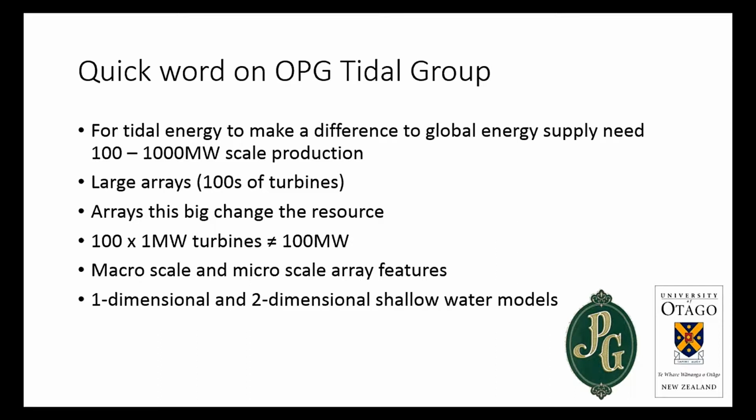That's because the turbines can slow the flow through the whole channel. Then you can also get effects within the turbines, so flow bypassing two turbines is fast, and you can catch that downstream and get more power out of that. So there's all sorts of macro scale and micro scale feedback loops and effects, and it makes it quite a complicated and interesting problem.